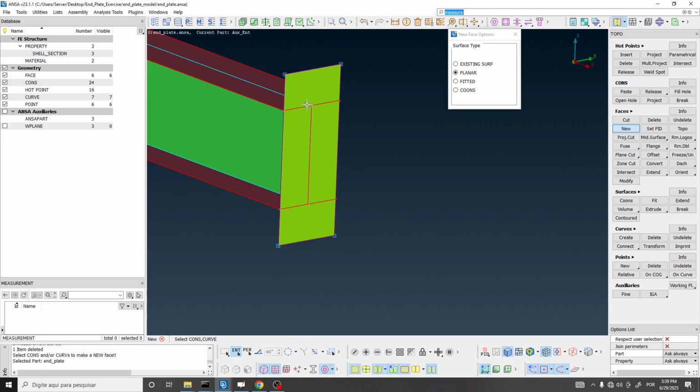All right. Now we need to create the holes. Usually when you're creating a plate with holes like this in a CAD software, you define a sketch and you draw the rectangle with the circles, and then you extrude, for example. So you do this in one shot, but in here we need to do this part by part.